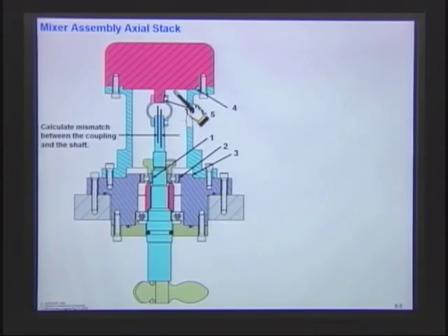So when I'm going to do these, I'm always going to find the worst case outer boundary. So when I'm looking at, for example, something like this motor shaft, I'm not only going to take the size of the motor shaft, but you remember this is where my datum was. It's going to tell me how much that was off. And I think if I remember, we have some .002 position on that. So I'm also going to take that into account, right? So it's going to take into account position and everything else. That's why we're going to do inner and outer boundaries, not just the size of them, but the actual location of the features too.